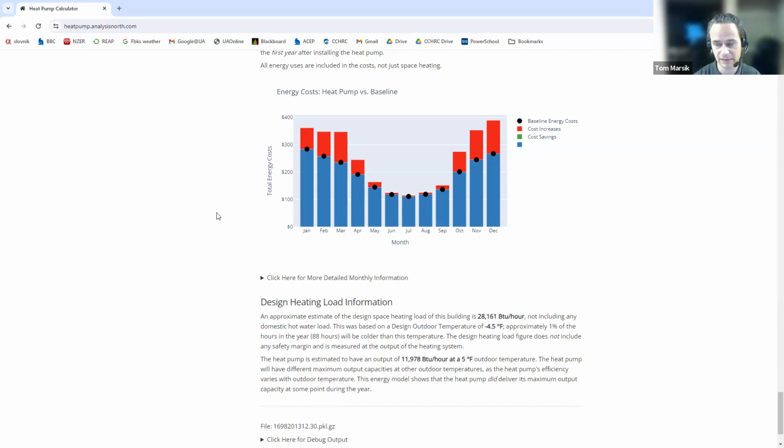Also, heat pumps are getting better. Another thing I should point out. So again, this doesn't mean you should forget about them, but this means that currently it's not cost effective, but there are certain things in the future that might change this conclusion. Natural gas prices might go higher. Also, you can be balancing out how much you are going to be using the heat pump in deep winter versus in the shoulder seasons. You can see in the warmer months, the loss here is getting lower. So those are the types of things you would play with as the factors are changing.